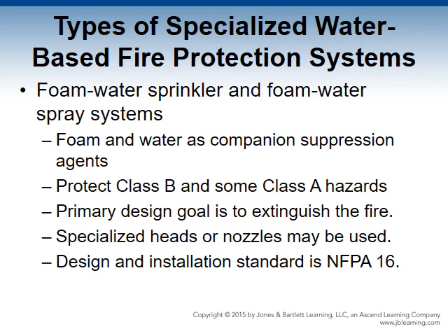Foam water sprinkler and foam water spray system components. The components and operational concerns are the same as those for the fire sprinkler system. The installation is also similar, with the exception that a foam water system might be a pre-primed system. The piping contains a foam water solution instead of water.